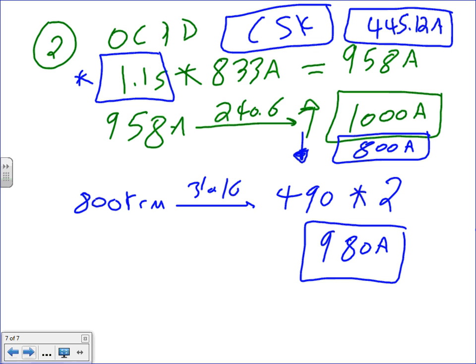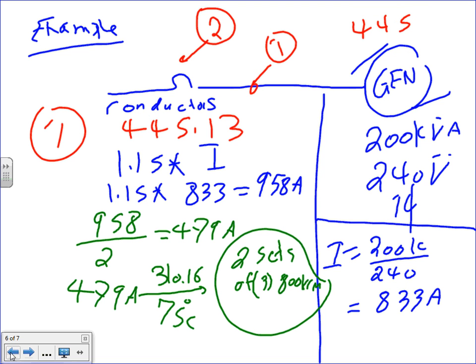The generator has its own protection for frequency, under and over. You tweak it so that if the frequency goes from 60 to 55, the generator will shut down. Almost any good generator sits with a controller. If the voltage is 480 and you overload it and the voltage drops to 460, or maybe 440, it will shut down. If you have 853 amps and you pull 900 amps out of this generator, the circuit breaker will not even wake up. The controller of the generator will shut down.